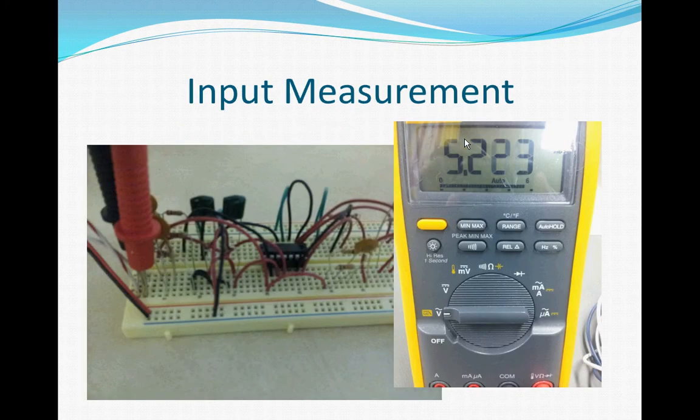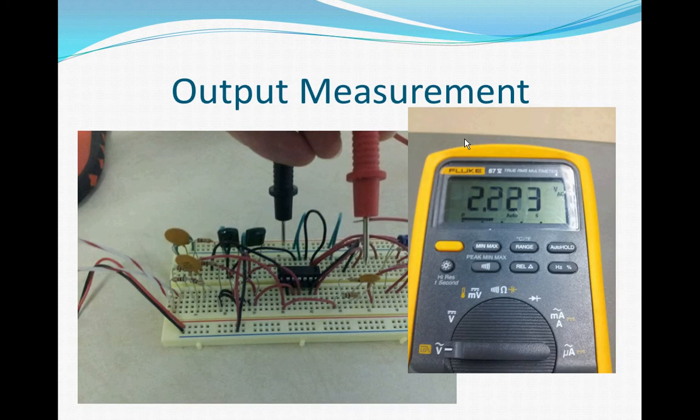Here we can see that supplying the 5.2 volts at the input side produces an output voltage of around 2.2 volts AC. From then, this value could be taken into an embedded computer, could be transferred out to a simple analog to digital circuit. Each one of those samples, we would find the RMS value as we sample it over time, because again, it is still an AC value. And then this value could be displayed back on the screen to a display in any of those forms.